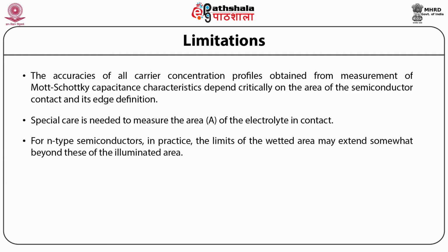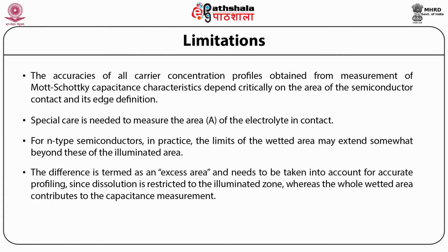For n-type semiconductors, in practice, the limits of the wetted area may extend somewhat beyond those of the illuminated area. The difference is termed an excess area and needs to be taken into account for accurate profiling, since dissolution is restricted to the illuminated zone, whereas the whole wetted area contributes to the capacitance measurement.